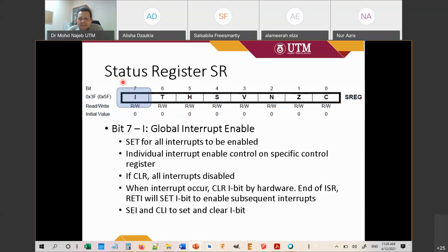You will see some registers later that might be read only, or might be write only. Usually we don't have write only. We can have read only, seldom. And here below we can see the initial values. When you turn on your microprocessor and it starts running, these are the initial values, which are basically all zeros. Okay, so that's on the interrupt bit in the status register.